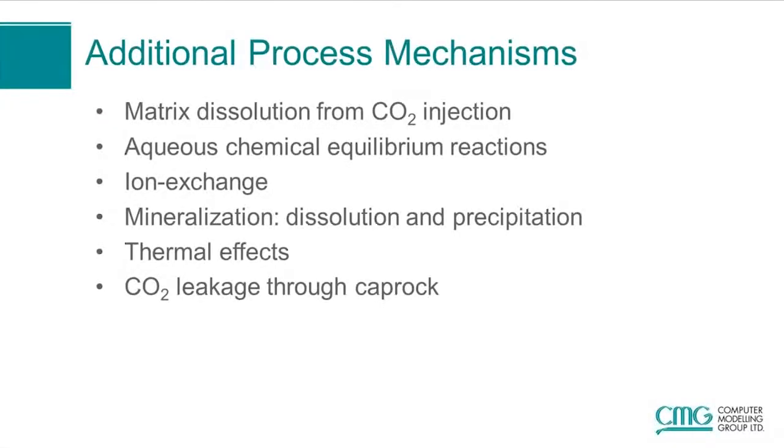So depending on the reservoir you're trying to model, the simulation model can be developed including some of these mechanisms or all of these mechanisms into a single simulation model. And you can do sensitivities on the relative impact of each of these mechanisms on the overall result of your simulation process or the recovery process.